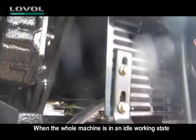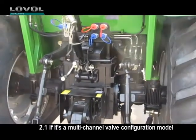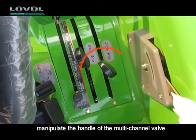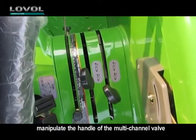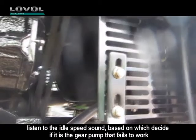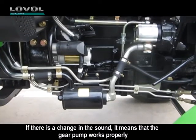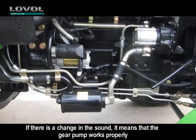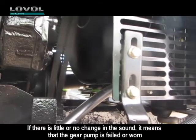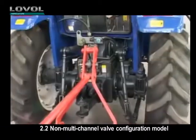When the whole machine is in an idle working state. 2.1 If it's a multi-channel valve configuration model, manipulate the handle of the multi-channel valve. Listen to the idle speed sound, based on which decide if the gear pump fails. If there is a change in the sound, the gear pump works properly. If there is little or no change in the sound, the gear pump is failed or worn.